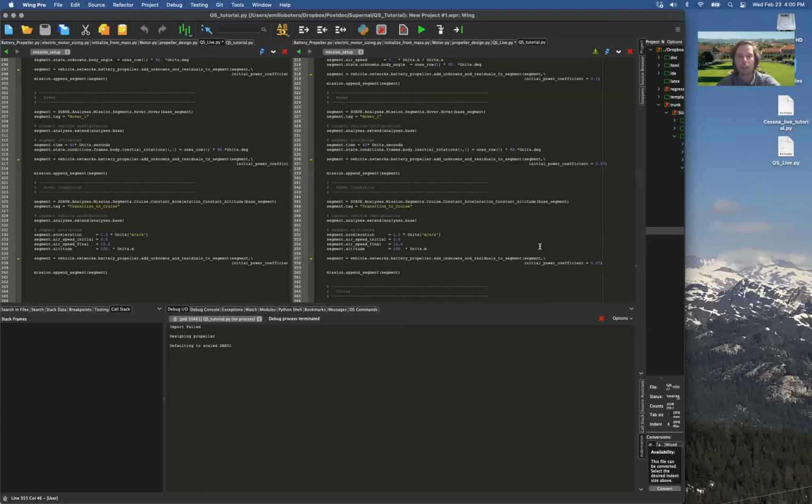Yes. So that'll be calculated, and it'll know how much is coming from one direction or the other. That's really the hard part here, because the blade element process ends up being kind of finicky: you have some flow that's directly into the rotor, and then some in the plane of the rotor. That ends up being the tricky part. That's why we just do numerically something that's like a simple transition. If you try to optimize, the optimizer tends to try something kind of crazy, and you get things that just don't want to converge as nicely. But it's numerically all doable, physically all doable.